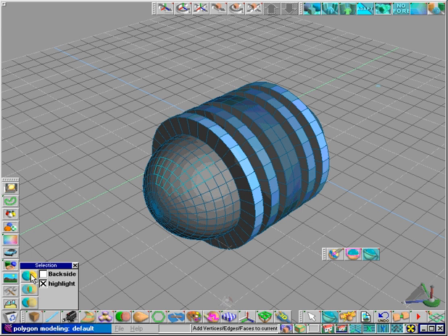With the Options panel, we can change the behavior of these selection methods. With Add to Selection checked, any subsequent selections will be added to the previous one, like so. Note that different selection methods can be used and combined to create the final selection. With the Select Subset checked, only portions of previous selections that fall within the selection window will be retained.